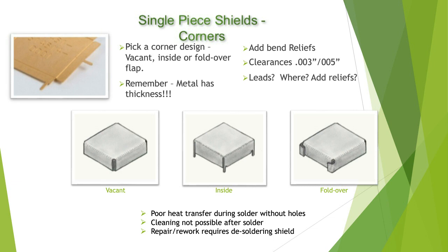So if you're trying to solder these things fairly soon after you've cut them out and bent them, it's going to tend to want to take solder pretty nicely. And if you engineer your clearance gap in there so it's fairly small, the solder will take a nice bead down the seam and it won't occupy any additional space inside or outside the shield. It will look nice and tidy and it will be basically a good corner.